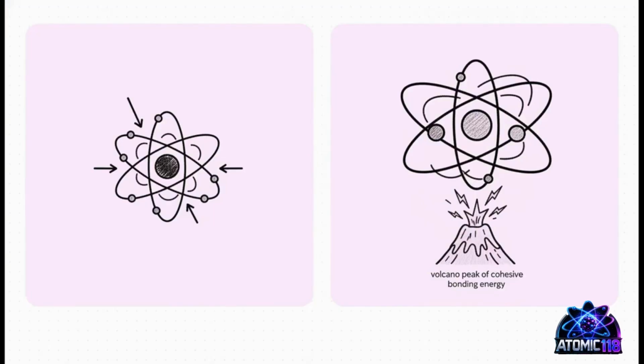To truly get a grip on these metals, we have to start down at the foundational atomic level. We need to look at how their electrons actually behave. It's super interesting because vanadium's contracted 3D orbitals behave entirely differently from the highly bonded 4D orbitals of molybdenum, and this single difference sets the stage for everything. Think of these orbitals as the electron clouds hanging out around the atom's core. As we move across the 3D transition elements, the increasing nuclear charge literally pulls those electron clouds tightly inward. They contract. Because of this, vanadium's smaller 3D clouds overlap pretty weakly with their neighbors.